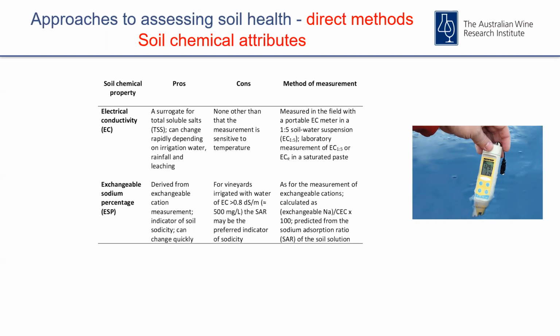The other thing is that you can tell a heck of a lot from changes in colour in the soil profile from a profile pit. When you see the phenomenon of mottling, which is orange-red mottles within a pale soil matrix, then you know that you've got at least temporary waterlogging at times of the year, and this indicates poor drainage. So there are ways of assessing soil permeability other than having to use a falling head technique, for example.